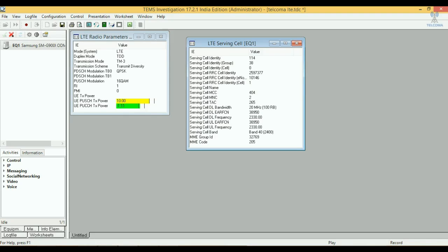So like this on radio parameters, if I am in post processing and capturing the radio parameters, I can say that my system is working on a QPSK modulation scheme. It is not working on the highest modulation scheme, which is 64 QAM. So accordingly, I will not get as much data rate as expected. Also my UE is sometimes getting yellow, green and red color. That means the power parameter of the PUSCH transmission is not that good, and similarly with the control channel.